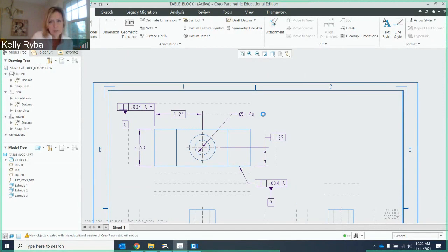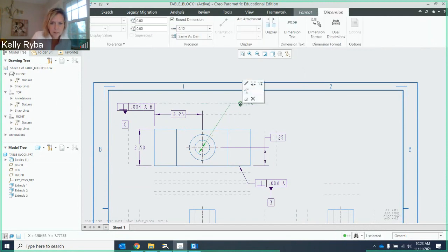And then I'm going to select that dimension after it saves. Now, because I'm home, sometimes that save function goes a little bit slower than normal. So let me grab this. I'm going to scooch it up here, and I'm going to click on it, and go to tolerance limits. First, before I put my values in, I'm going to switch it to 4-place decimal. And then I'm going to put my actual value here.